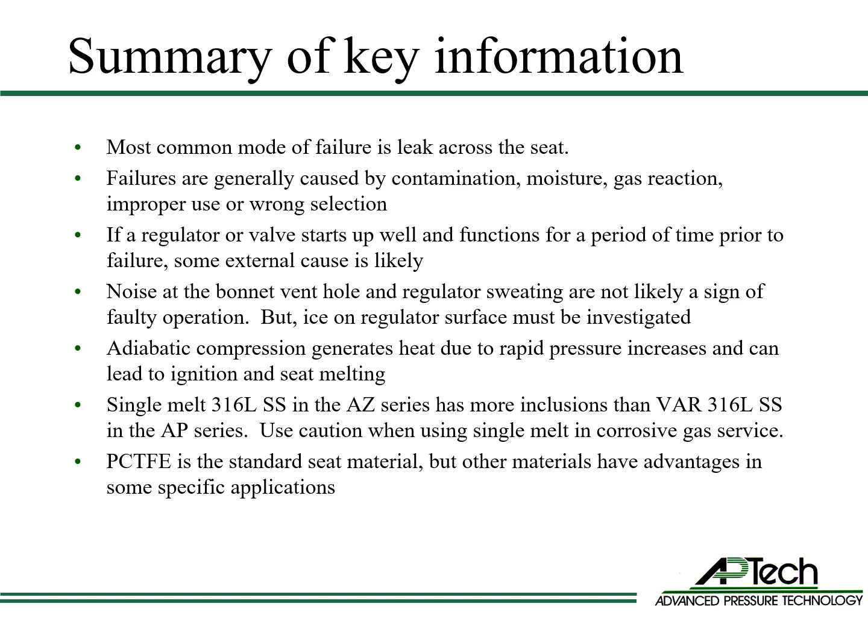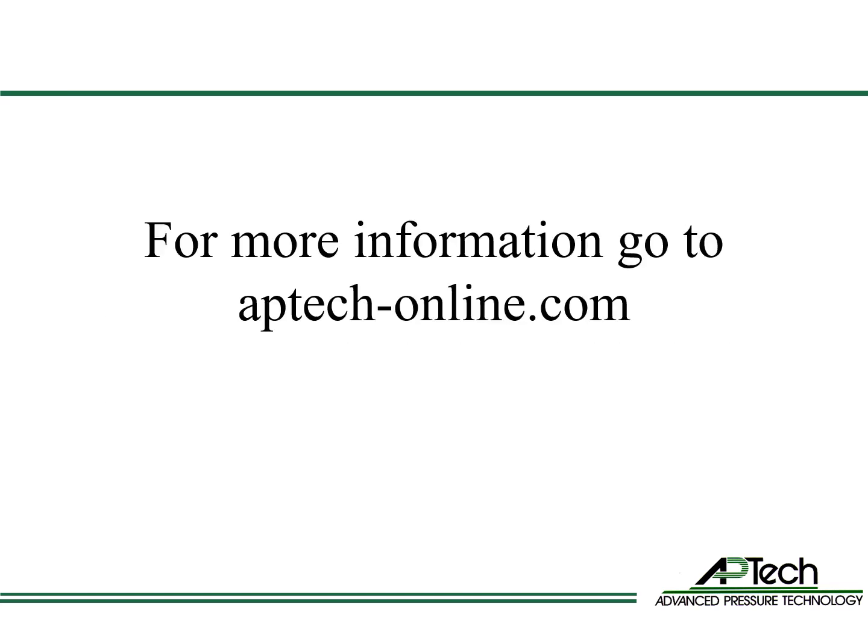Adiabatic compression generates heat due to rapid pressure increases and can lead to ignition and seat melting. Single melt 316L stainless steel in the AZ series has more inclusions than VAR 316L stainless steel in the AP series. Use caution when using single melt in corrosive gas service. PCTFE is the standard seat material, but other materials have advantages in some specific applications.